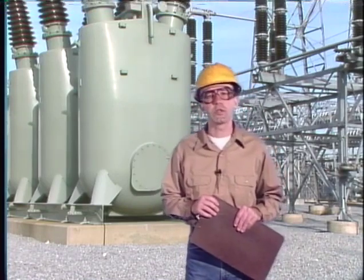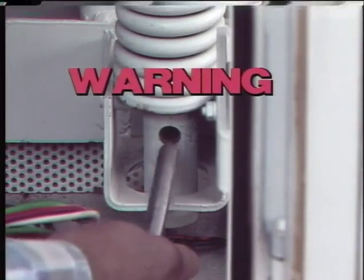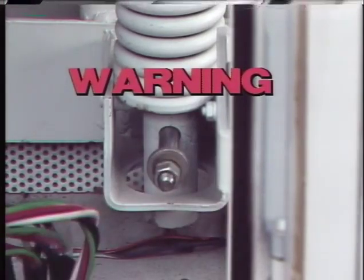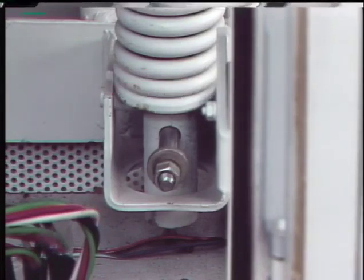In this part of the program, we're going to look at some general maintenance that applies to most breaker operating mechanisms. Then we'll look at some specific tasks for solenoid and motor spring operating mechanisms. A word of warning is needed here. For most mechanism maintenance, the source of stored energy should be blocked or discharged to keep the breaker from closing and to prevent injuries from accidental operation.